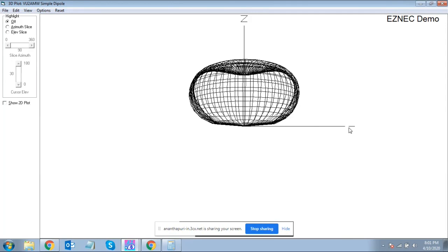The x-axis is parallel to the screen, and in this software we call it azimuth 0. In many other software, usually the angle starts from the north. The top is your north, labeled as 0, and then some software count clockwise, 10 degree, 20 degree, 30 degree, and some software anti-clockwise. Let's go with the convention used here. The positive x-axis always starts with azimuth 0.